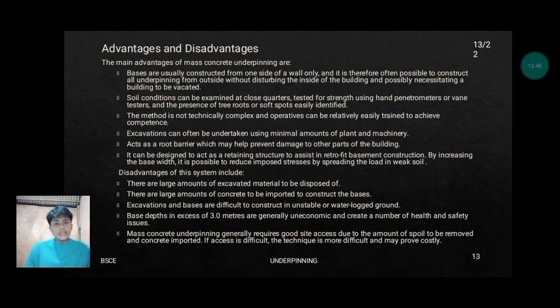Also, the method is not technically complex and operatives can be relatively easily trained to achieve competence. Next, the excavation can often be undertaken using minimal amounts of plant and machinery, and it acts as a barrier which may help prevent damage to other parts of the building. And lastly, it can be designed to act as a retaining structure to assist in retrofit basement construction. By increasing the base width, it is possible to reduce imposed stress by spreading the load over the weak soil.